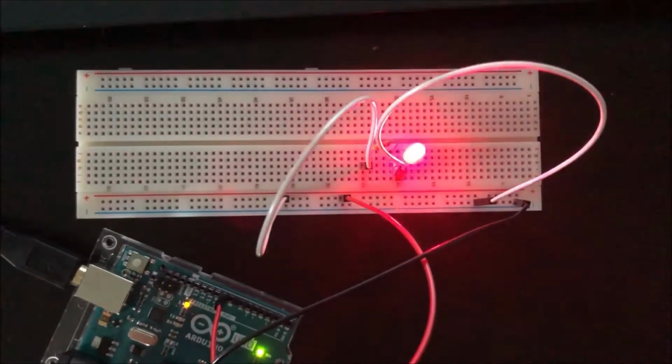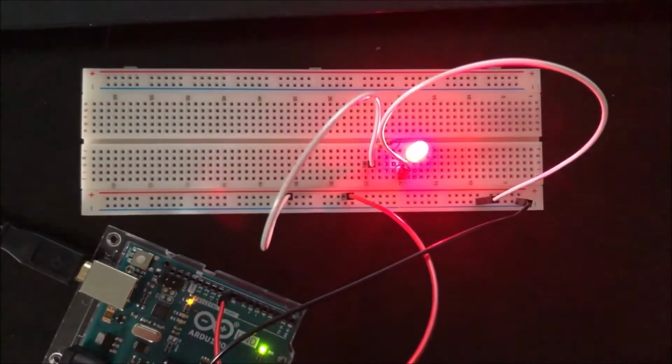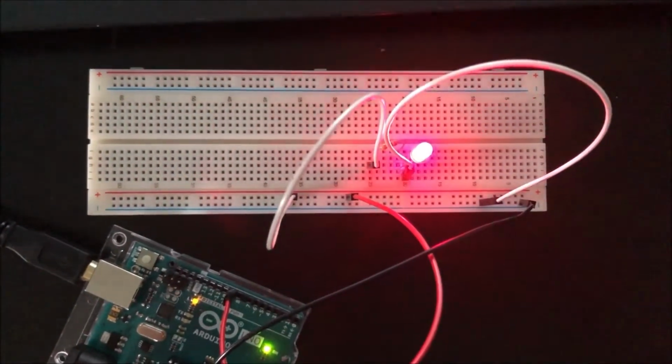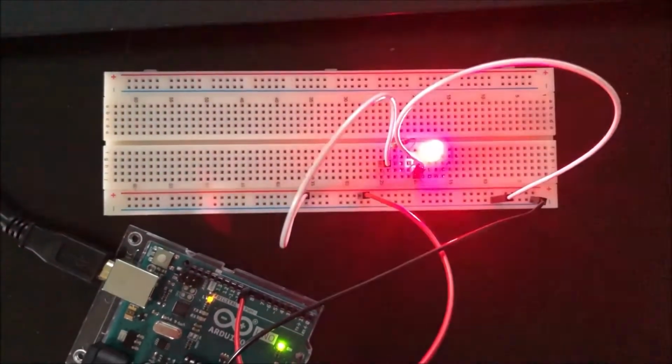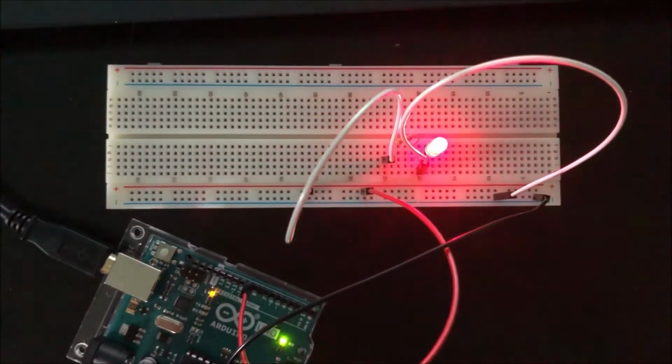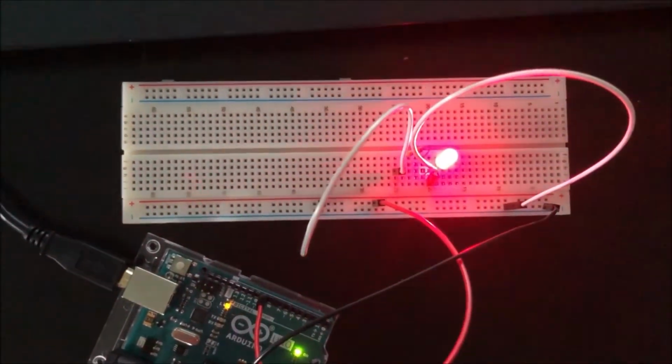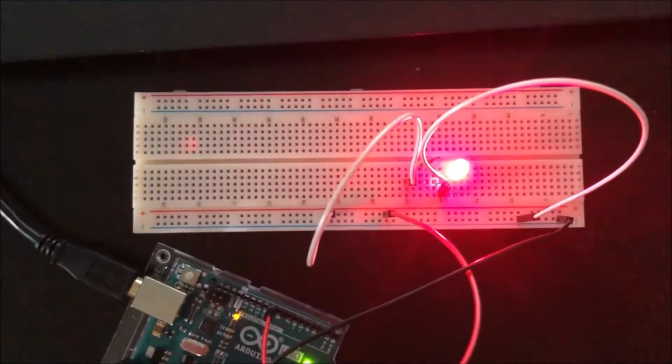So for my manual fade function, I used digitalWrite commands instead of analogWrite commands to get the LED to dim and brighten as it had done previously. In order to do this, I used a series of for loops. In these for loops, the i value is the duty cycle.